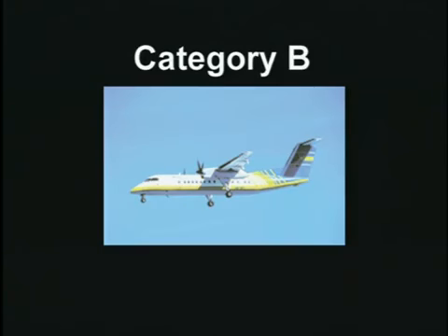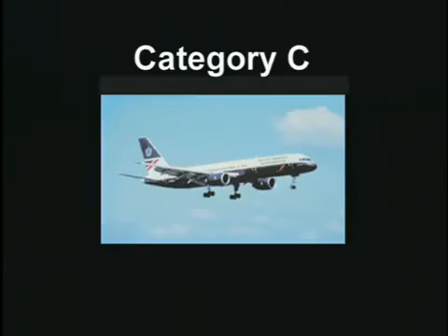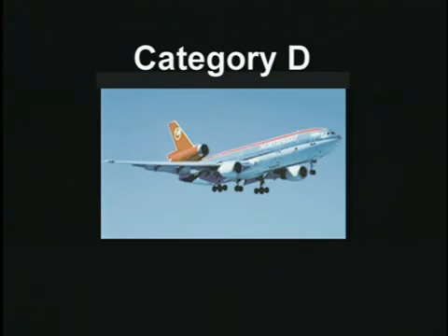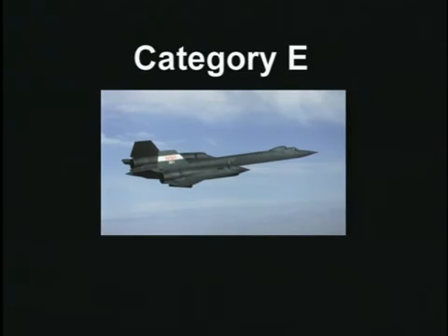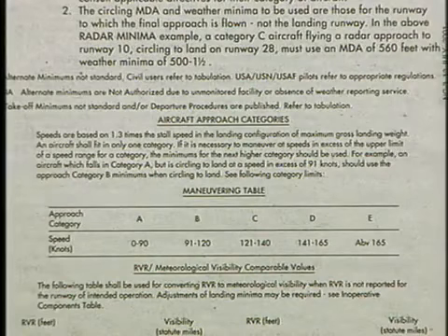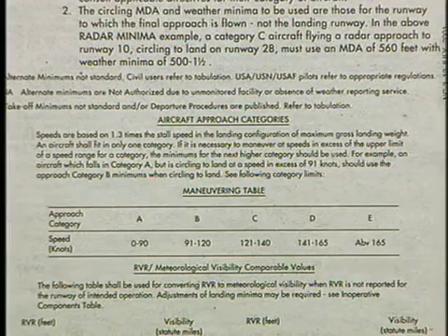Therefore, the FAA has established 5 approach categories based on approach speed. A letter designates each, with A being for the slowest approach speeds and E for the fastest. For most airports, Category E is not shown since it applies primarily to fast military aircraft. The airspeeds that define each approach category are listed in the front of the approach chart booklet.